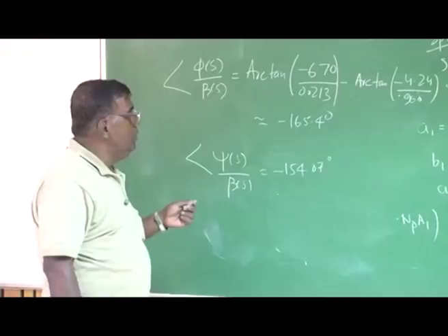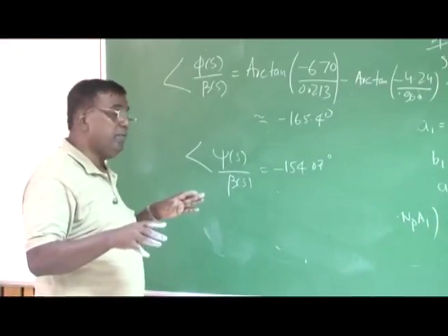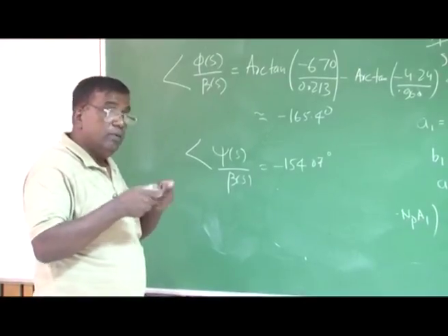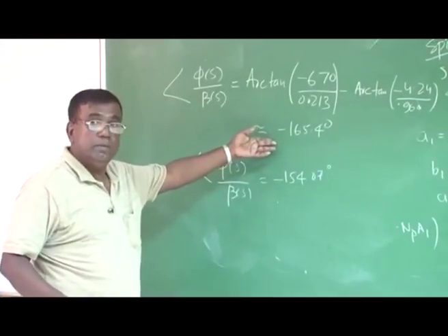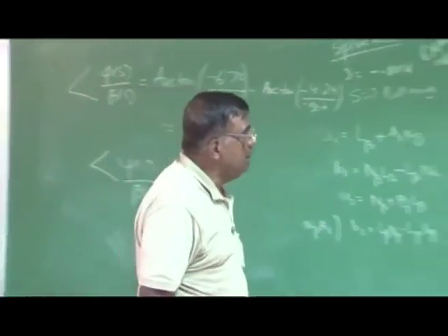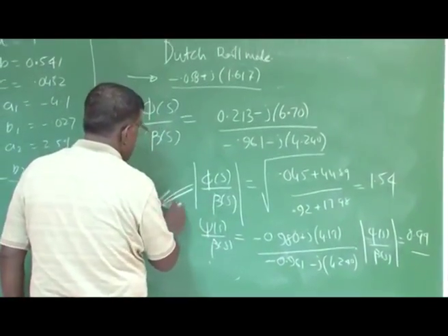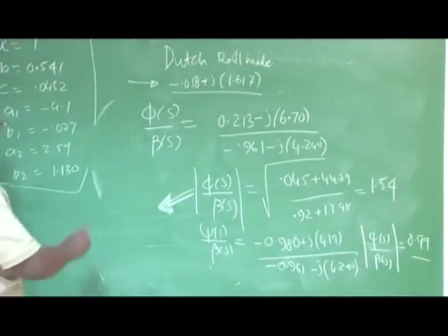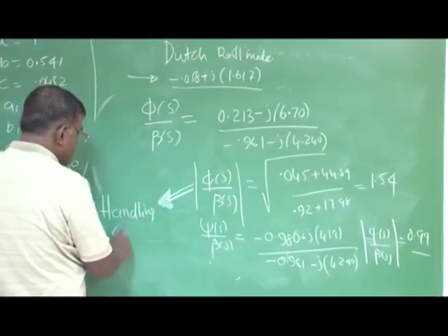So you know relatively how psi and beta are functioning in terms of their phase differences. They are definitely not in phase, they are out of phase, right? Almost 180 degree out of phase, opposite, right? This is one. And second thing, you understand that for me, this is important: phi and beta, this transfer function or this mode shape, typically for handling quality requirements.